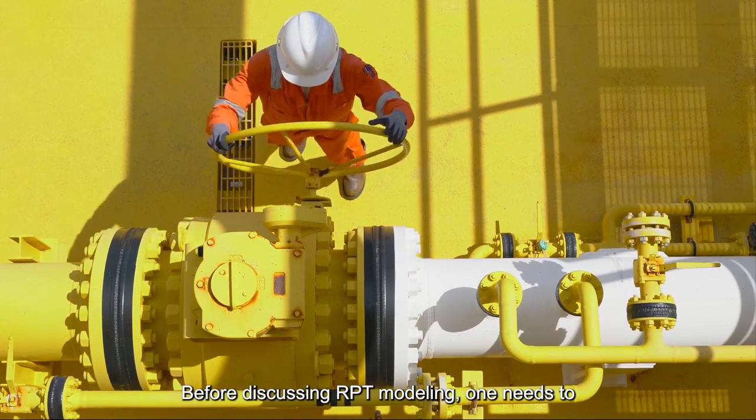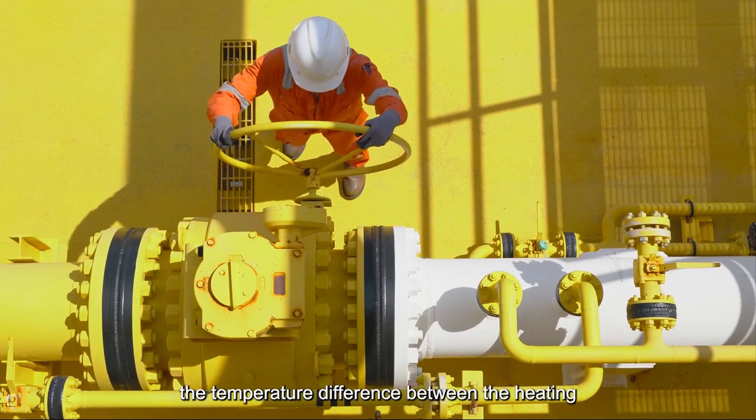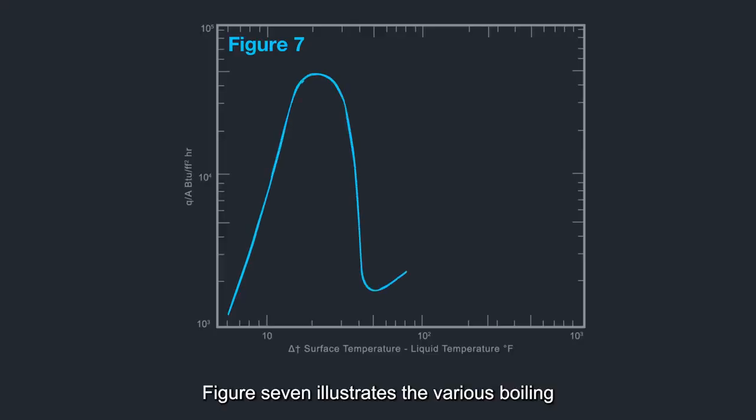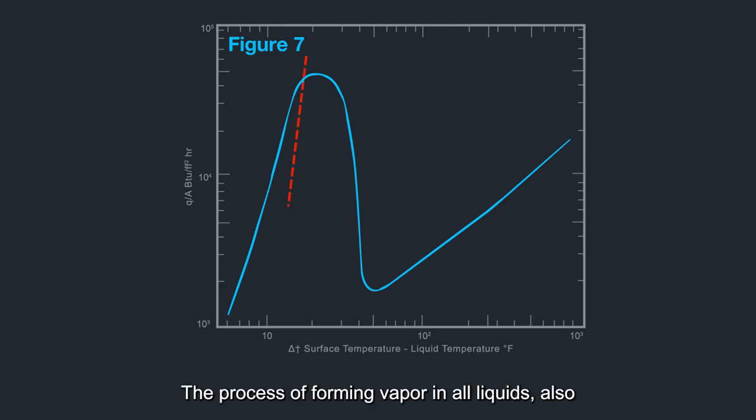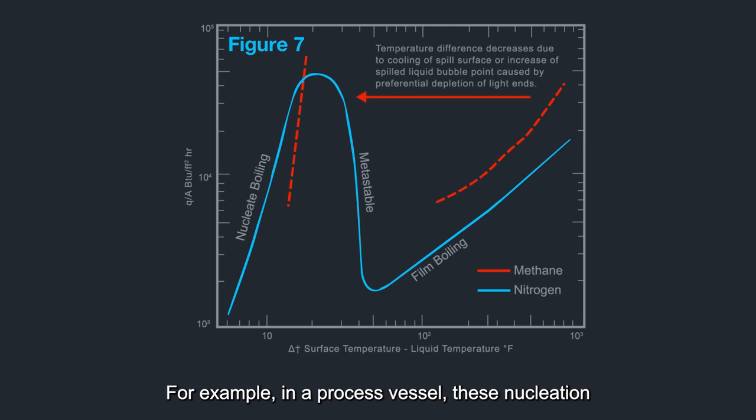Before discussing RPT modelling, one needs to understand the different boiling regimes based on the temperature difference between the heating surface and the liquid. Figure 7 illustrates the various boiling regimes for LNG and nitrogen spills. The process of forming vapour in all liquids, also referred to as flashing, usually involves what is called nucleation sites. For example, in a process vessel, these nucleation sites can be small imperfections on the vessel inner surface, or tiny colloidal suspensions of dirt or dissolved gas in the liquid.